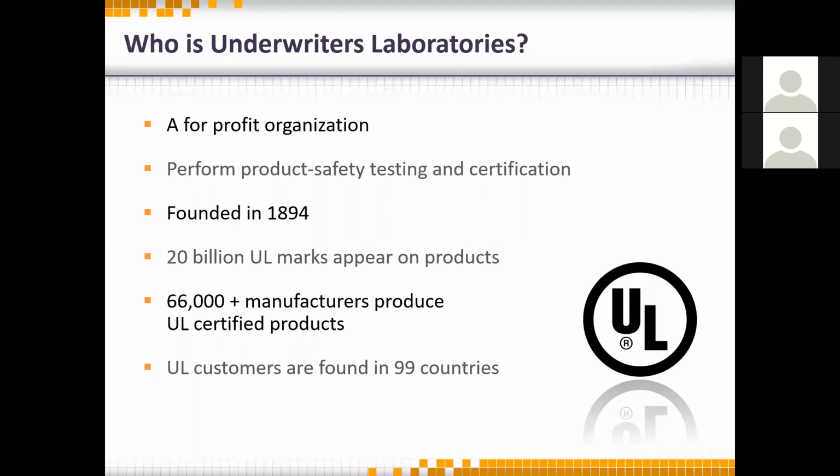There are several independent labs throughout the country that will do the ASTM E119 fire testing and come up with some fire designs, and they are code approved. Those can be found in the GA600. The real name for that book is the Fire Resistance and Sound Control Design Manual. It is published by the Gypsum Association.